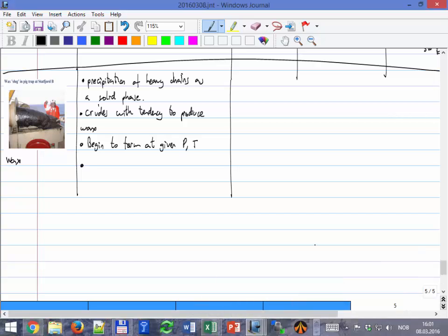Also, something very important about wax that we mentioned yesterday: remember that the wall has to be cold for it to stick to the wall. So, cold wall. And when we say cold, it just has to be colder than the fluid. And we have actually three phenomena: precipitation, agglomeration, and deposition. Okay, again, people say it's not so dangerous that the crystal of wax appears, but the problem is when it sticks to the wall and then you have accumulation over time.